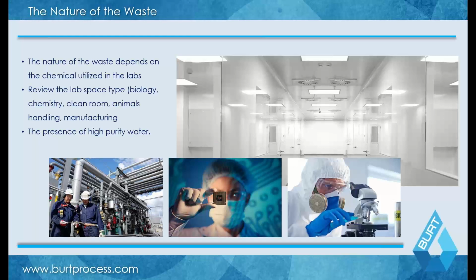That's because even if you size it for an average flow rate, it's when you have that higher flow rate that you run the risk of having the out-of-spec condition. And obviously, out-of-spec conditions, when it comes to treatment systems, can be very detrimental. If you do project future capacity needs, you can oversize the system a little bit. That's a discussion you need to have about long-term maximum waste profiles.